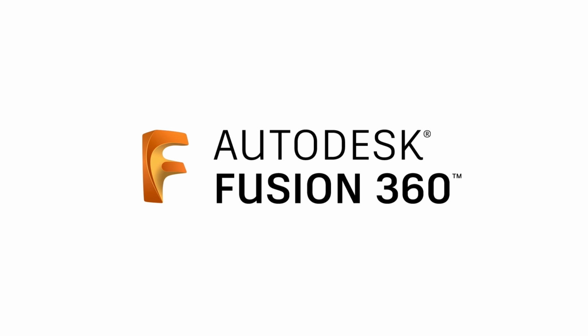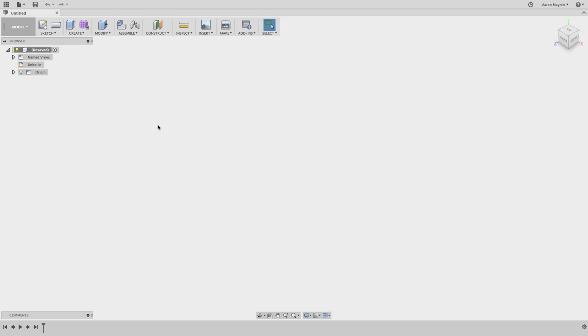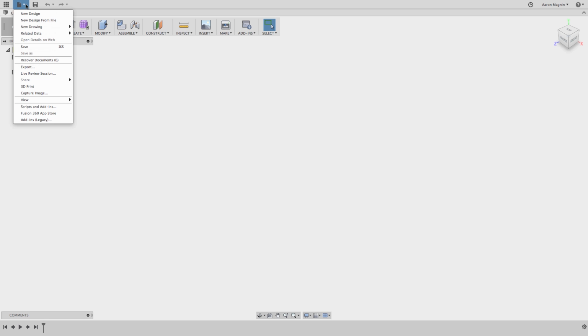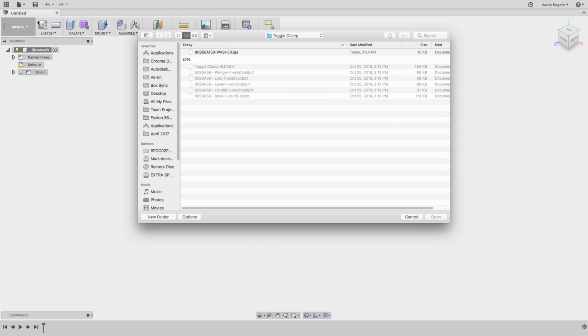In this video, I'm going to show you how to import your files from other systems and vendors, and give you a jumpstart on your next design. If you're like most new Fusion users, you probably dove right into the File menu looking for Import or Open options there. We don't have that, but the next closest thing is New Design from File. When you click this, you're taken to an Open dialog, but it can be somewhat misleading.